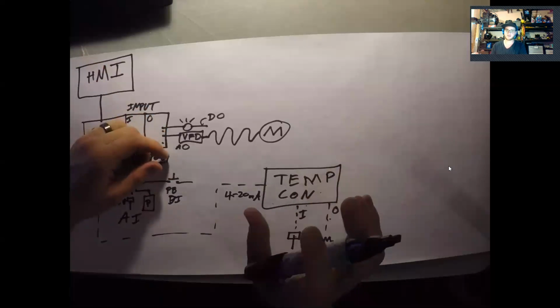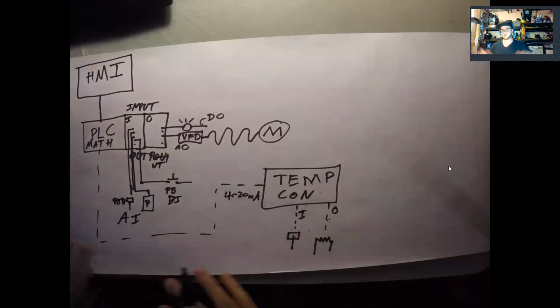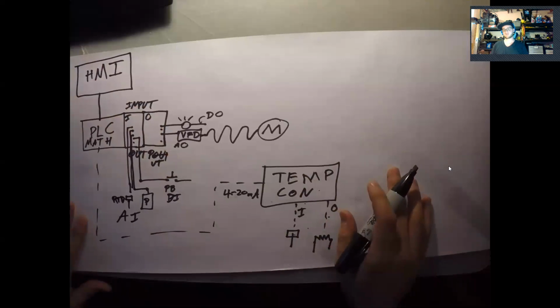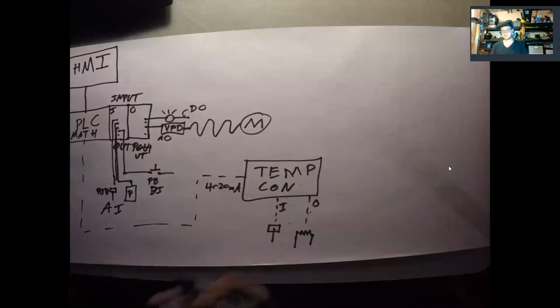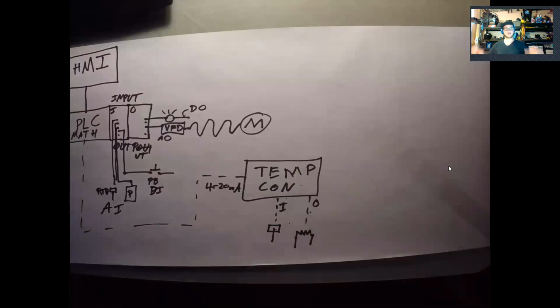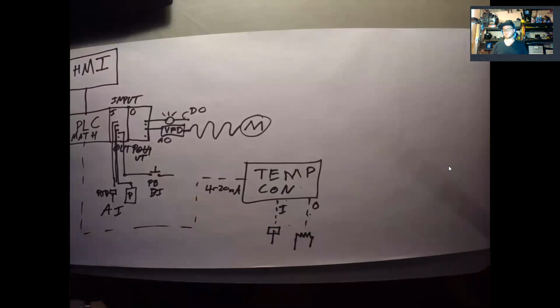And so that'll usually come with a skid-based controller, which is usually a PLC. Now, if you have this big industrial plant where that's just one unit operation, right? So let's say an air compressor, it's a skid-based air compressor. Well, you're also going to have a plant-wide control system that there's different platforms available.